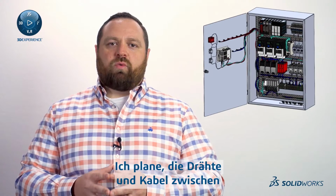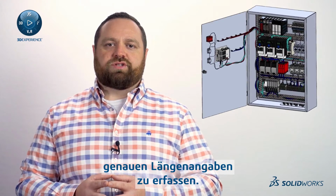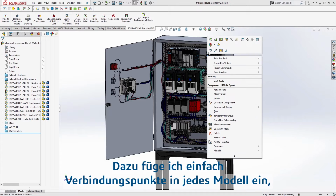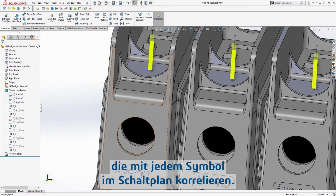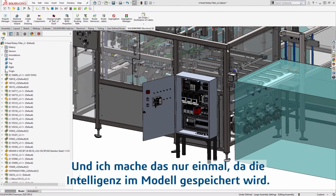I plan on routing the wires and cables between all the components to capture accurate length information. The components that I am routing between need to be what I like to call electrically intelligent. To do this, I simply insert connection points into each model, which coincidentally correlate back to each symbol within the schematic. And I only have to do this once, as the intelligence is saved within the model.